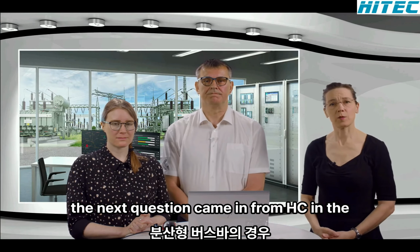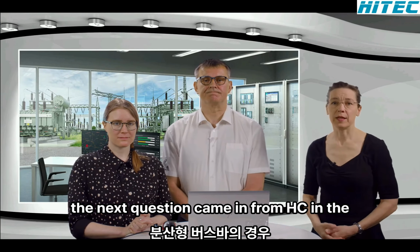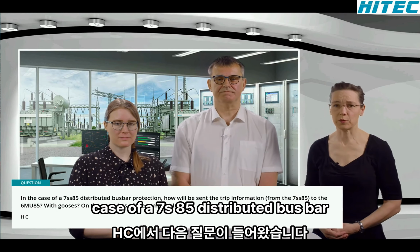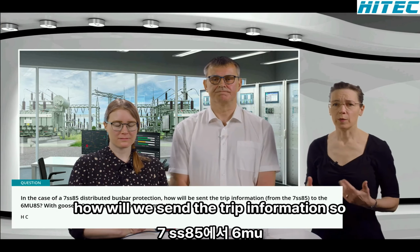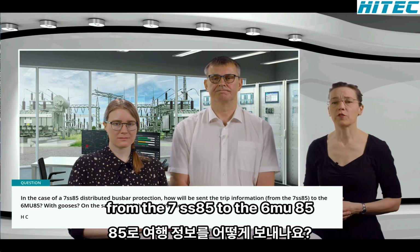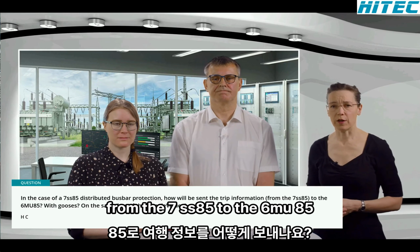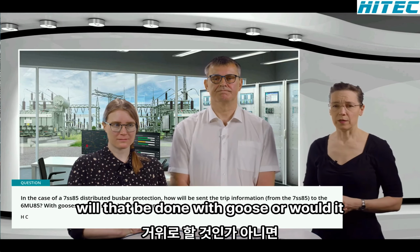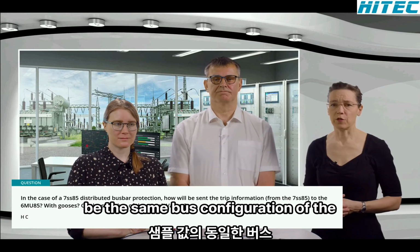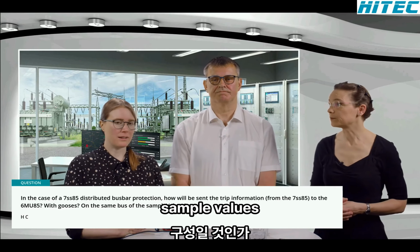And then the next question came in from HC. In the case of a 7SS85 distributed busbar protection, how will the trip information be sent from the 7SS85 to the 6MU85? Will that be done with GOOSE, or will it be the same bus configuration as the sampled values?